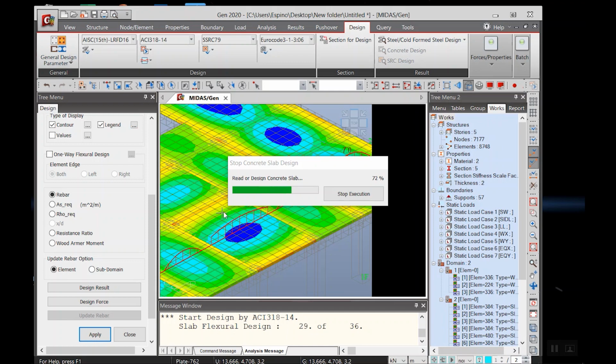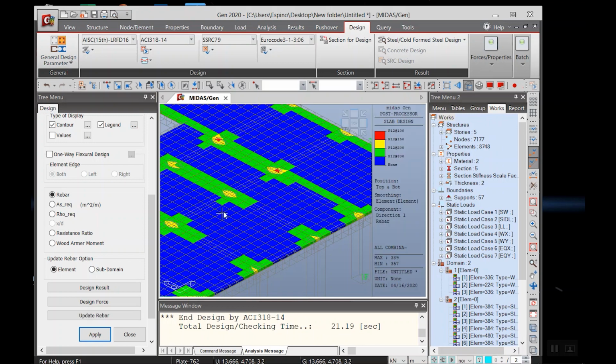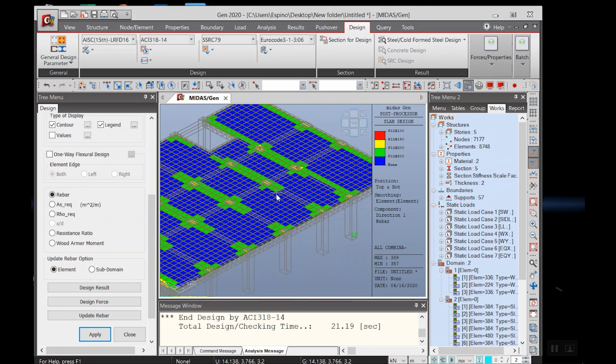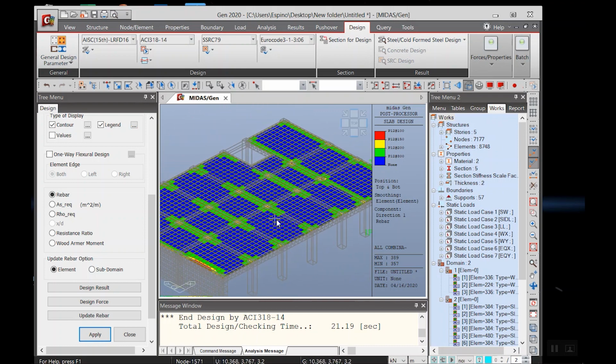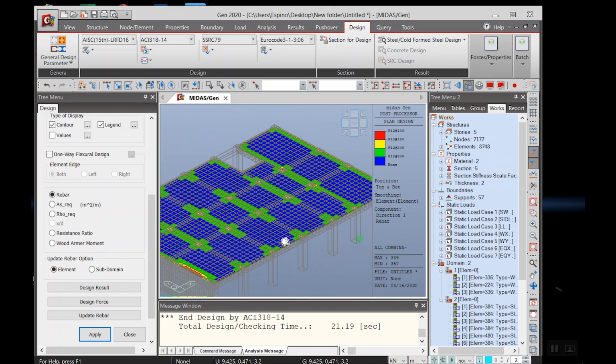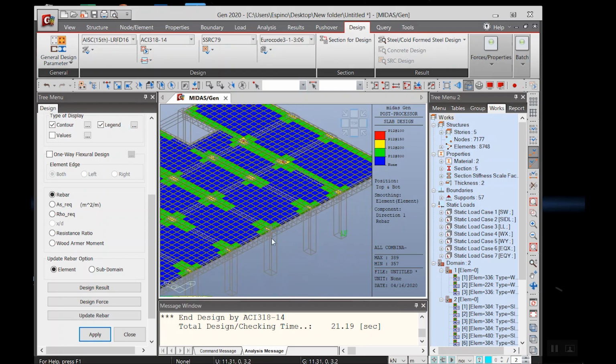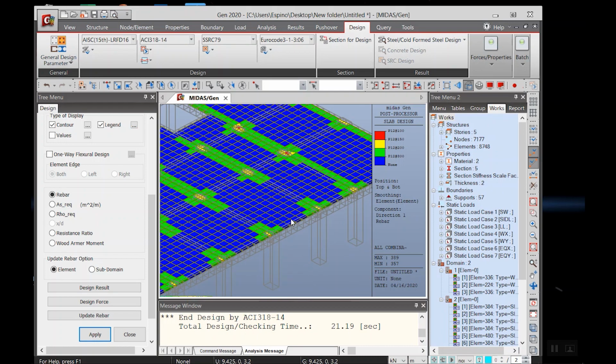Of course, having a finer mesh means having a more exact result. But of course, with a fine mesh you will also have to consider the post processing or analysis time that the computer will use, since many elements mean a larger analysis time.